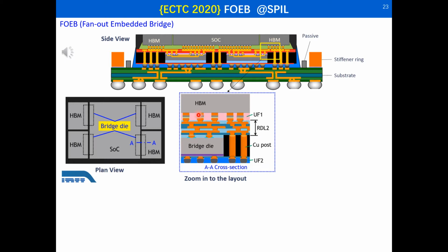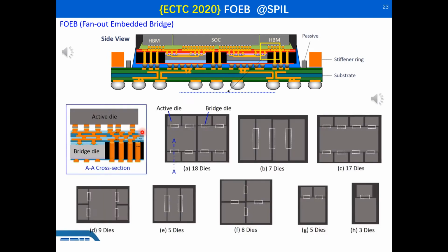The active dies, such as SoC chip and high bandwidth memory dies, are connected to the bumps using the flip chip method, and underfill, and then all of these are molded together to attach to a package substrate. This method is useful for producing high-density interconnects using embedded die and RDL, and it is very flexible for multi-die integration.